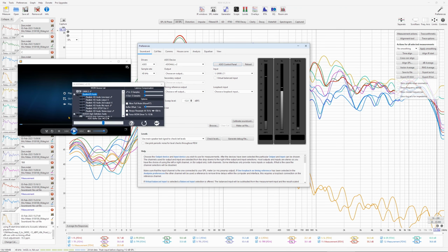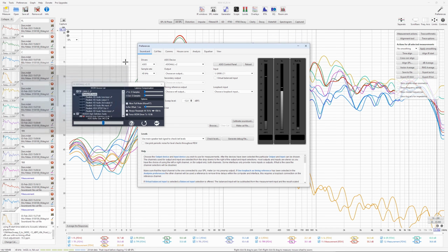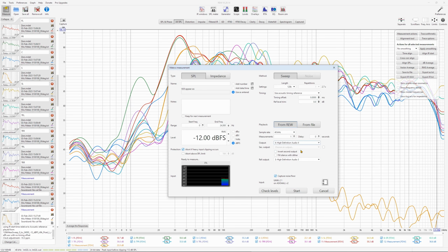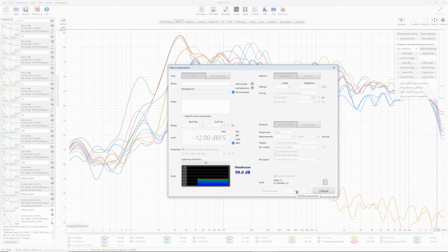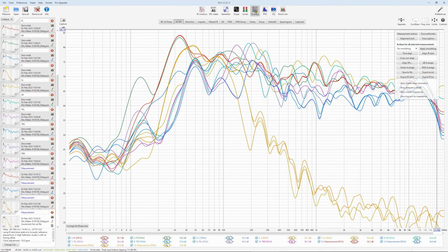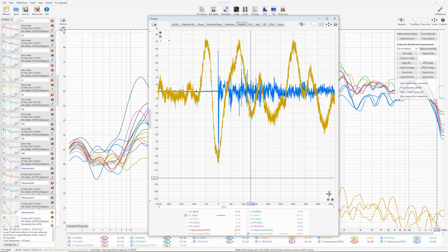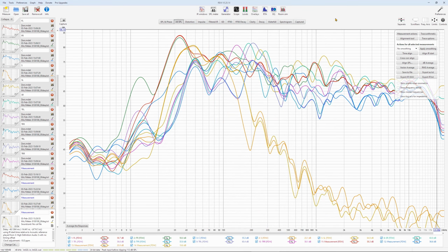measure this properly. Put the ASIO drivers back, close Windows Media Player, reload, so you get rid of this red cross sign there, and then measure sub from REW. Yeah. This is now perfectly aligned subwoofer with the rest of the system. So that's all for speaker distance settings.